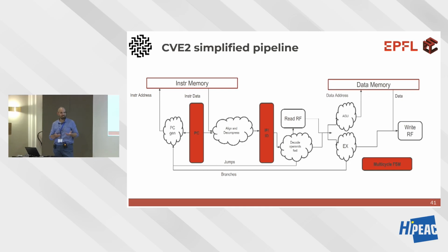At least 2. The first one, I know whether to branch or not. And then the second cycle, I calculate where to branch, in case I need to branch. That's why I'm scheduling them like this, because if I don't have to branch, I don't do it, right? And I continue with the next instruction, and I don't lose cycles at all. So non-taken branches are good for me.